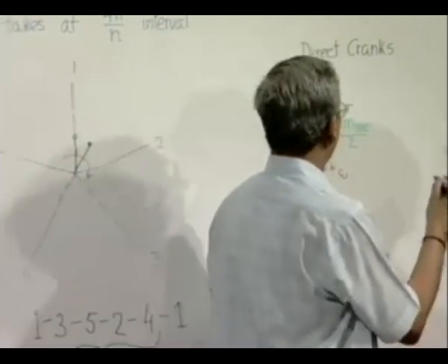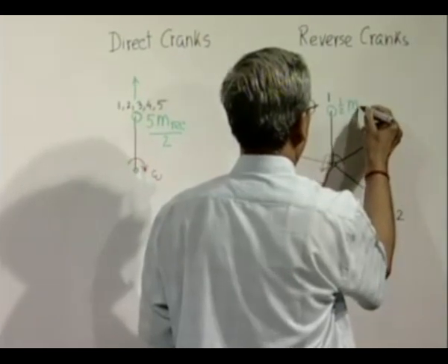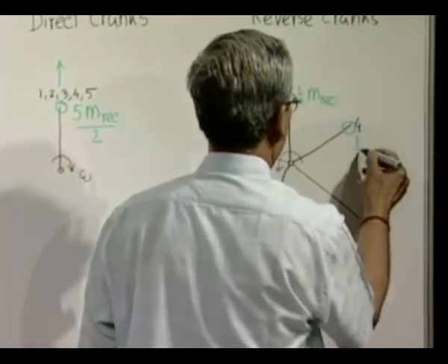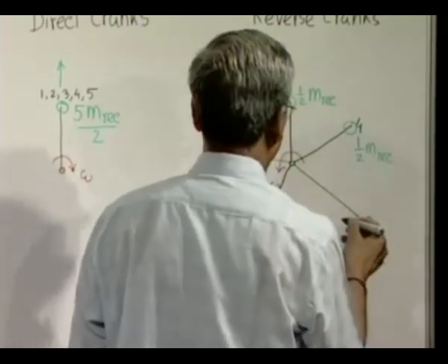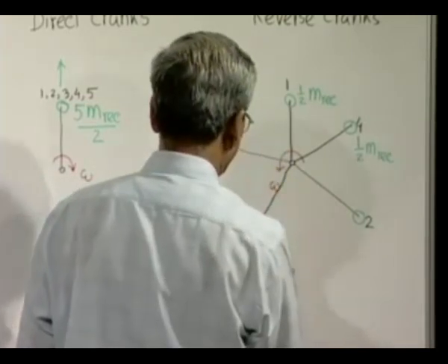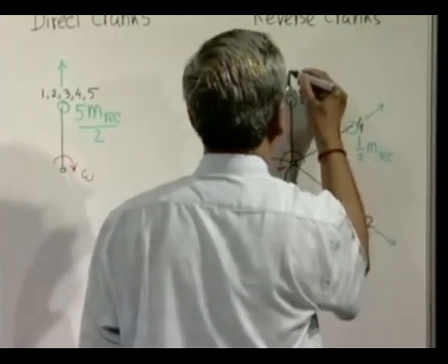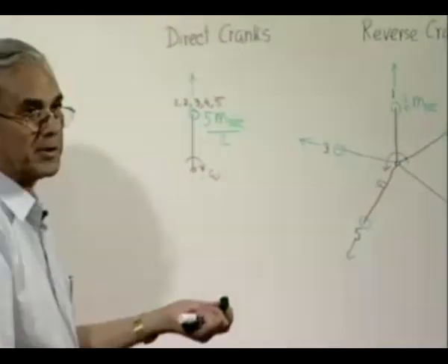On the other hand, when we place half m reciprocating here, half m reciprocating and so on, then these centrifugal forces produced by these imaginary masses neutralize amongst themselves.